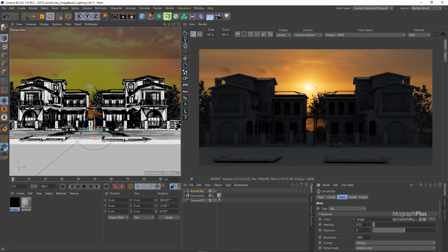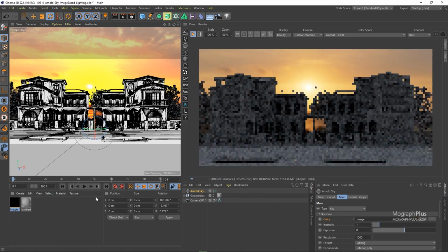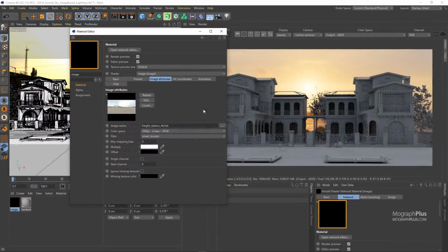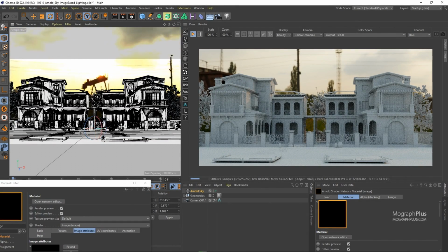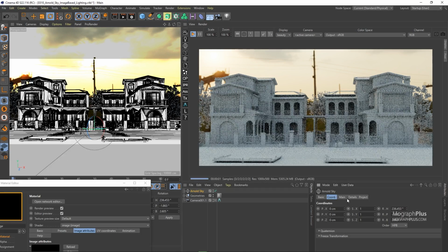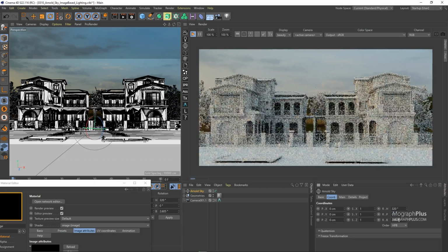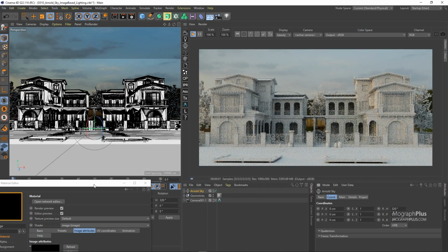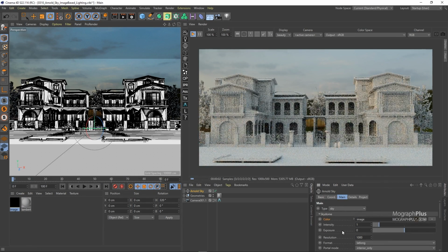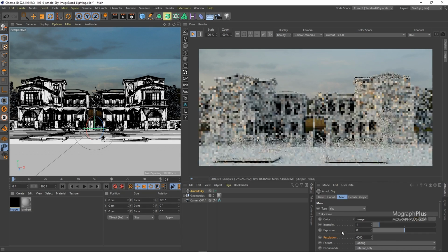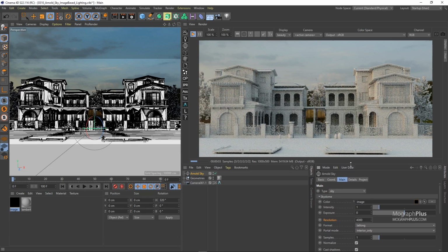Let's use another HDRI. You can load this Fright Station HDRI, which is a free HDRI from hdrihaven.com, and set the rotation to around 320 degrees probably. And now we get a completely different look, which is incredible. Then we have resolution, which we discussed, and you should set the resolution close to the actual resolution of the image. The HDR I'm using is about 4000 pixel wide, so we can type in 4000, but for faster renders, let me just leave it at 1000 for now.